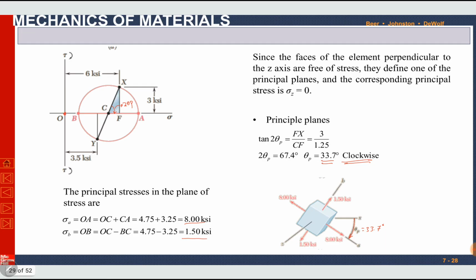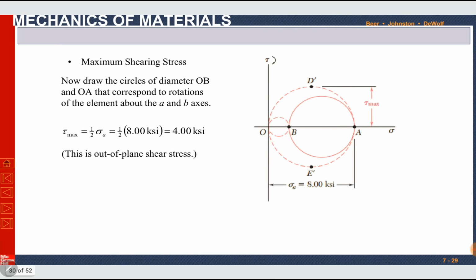So the third stress is here, always at the origin, remember it. Join it with point B using a dotted circle, and then with point A using another dotted circle, like this. In this case, our maximum stress is out of the plane. It is of the dotted circle. Remember it, out-of-plane circles must be dotted ones for a Mohr circle for a state of plane stress.